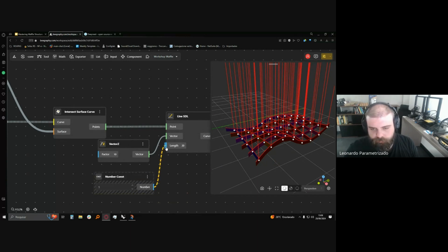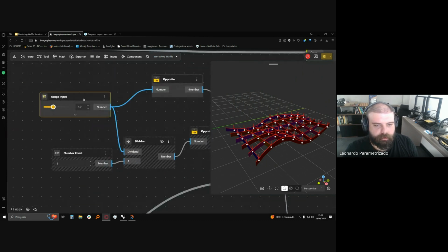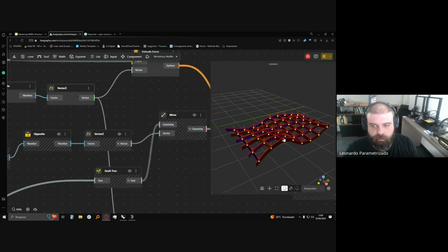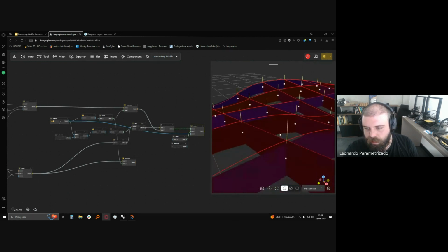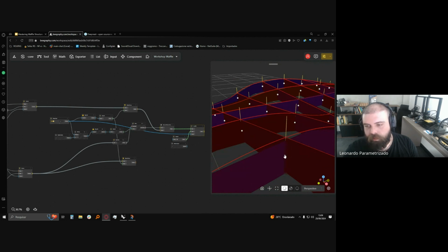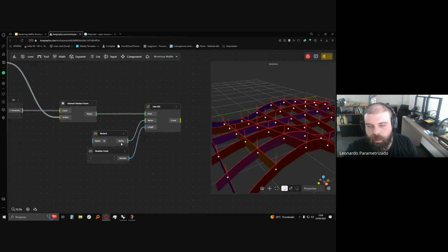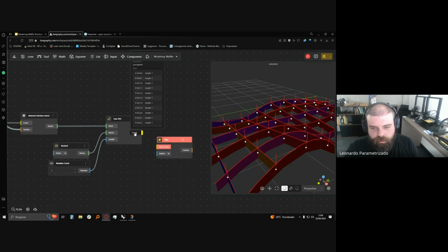That can work. Or you guys can do this more efficiently, and you can grab this value here, which is the height of our beams, and put it here, so it always goes through all of our height here, okay? But I'll be leaving number 1 for now. It's fine. And then I'll be creating a pipe here with this curve.